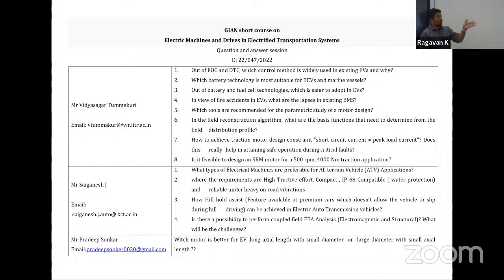So ANSYS can do all the simulations, but whether they're truly going to be coupled, we've actually even had some challenges where when we went above a certain frequency, above 5,000 hertz, ANSYS was not putting out the right magnitude. Our decibel levels and our vibration frequencies were not reading properly. So we had some challenges there that we found out several years back. It's a good option definitely. You can look at it, but you have to have the exact dimensions of your structure. That's a whole other thing, which is possible, but a manufacturer has to provide it to you.